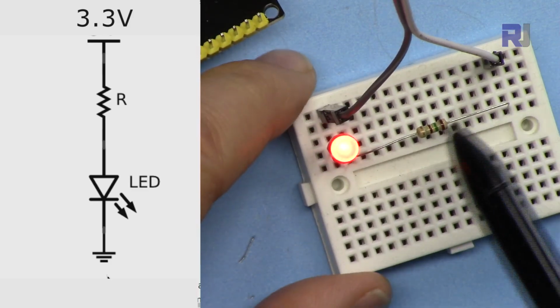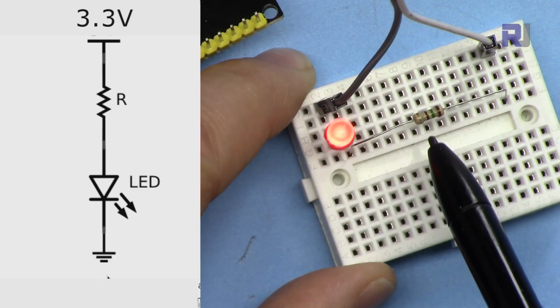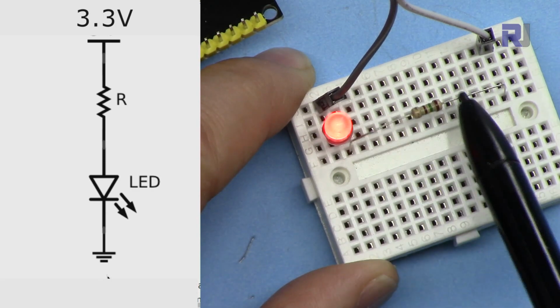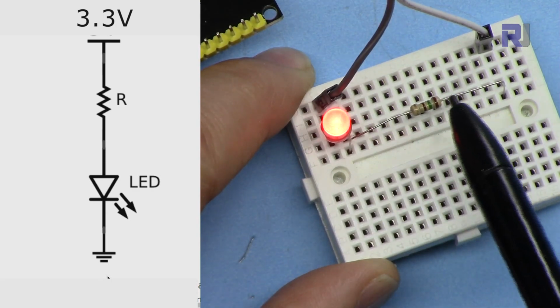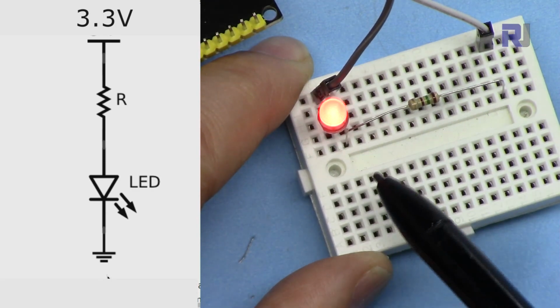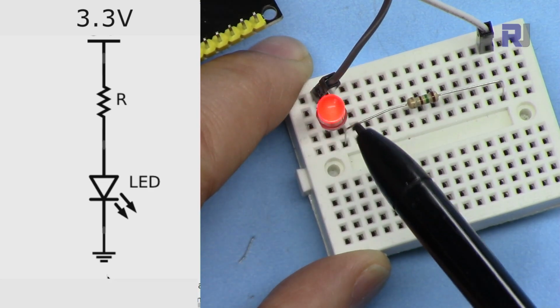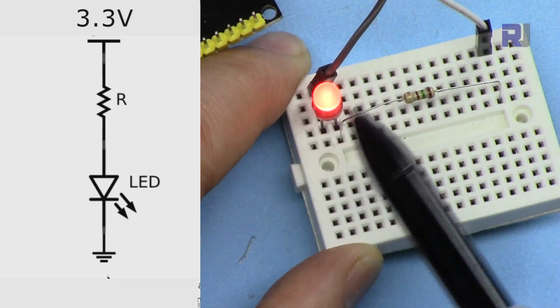And in this case, I've used one LED. If you do the calculation, it's 130 ohm, but the closest one I have is 150. Do not go lower, go a little higher. It will be a little dimmer, but it is still better to protect the LED.